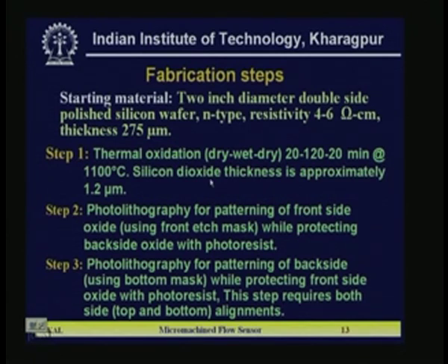The rest of the portion you are removing the silicon dioxide, so that when you etch from the backside, from the top side also, those layer boundaries will also etch, so that easily at the end of the process you can break the wafers or break the samples from the wafer easily. Sample means sensor devices, easily you can break it. That is why this step 2, front side patterning, is required. And what patterning are you doing? It is oxide patterning, and on the periphery of each sensor, some line which we also call a scribe line, the oxide is removed.